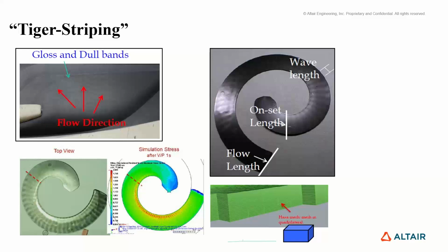And if that's what's making it go away, it's not just geometry that's causing the tiger striping, it's the fact that the vents aren't clean, which means air is involved. And so if I think about another analogy, and you can do this on your own if you like, take a piece of copper tube and a small stack of round neodymium magnets and drop them in the copper tube, and you will see them bounce and bounce as they work their way down. As they speed up, they create eddy current, which then resists the falling of the magnets until they stop.